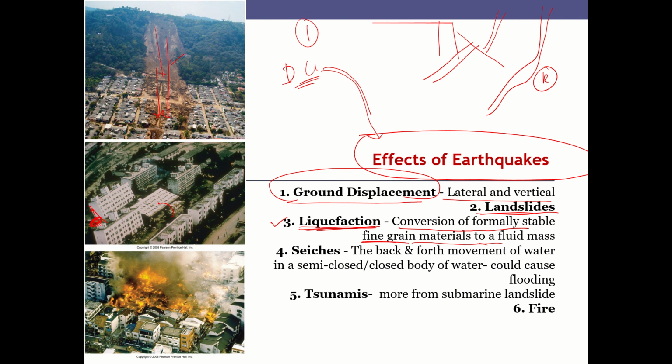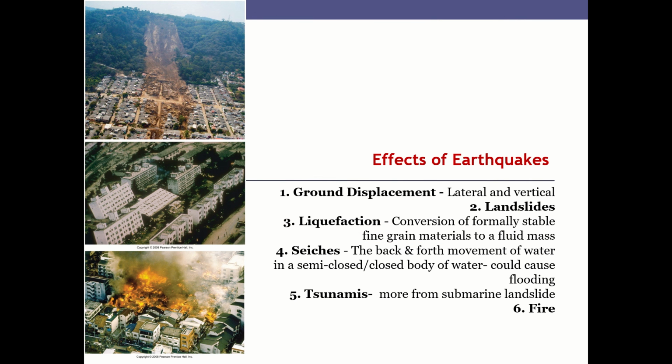Okay, this particular building, that is because the soil bearing capacity of that particular soil is no longer taking the load which it is supposed to take. Okay, so this can happen because of liquefaction. I have explained before also, but this is one of the important concepts that we should keep in mind: conversion of formerly stable fine-grained materials to a fluid mass.